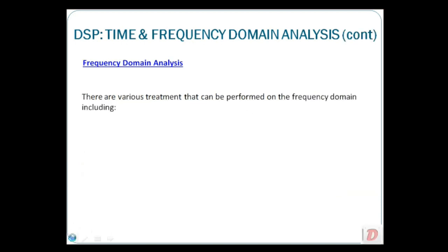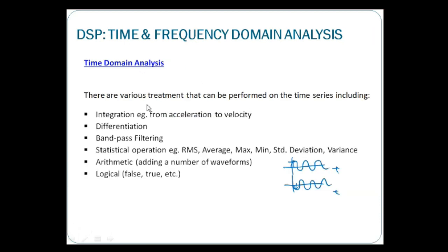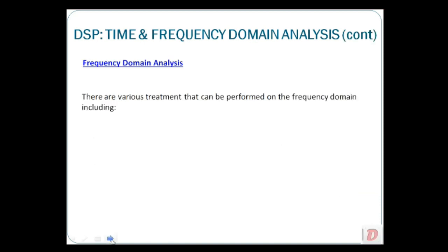And that is some of the time domain analysis that can be performed when your signal is a time series. Whereas in the frequency domain, as I mentioned to you, the spectrum itself is very useful information that we can use to analyze vibrations or machinery faults. I mean, use this vibration as a parameter to diagnose